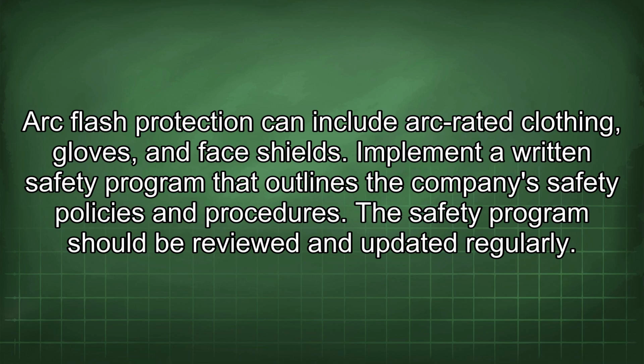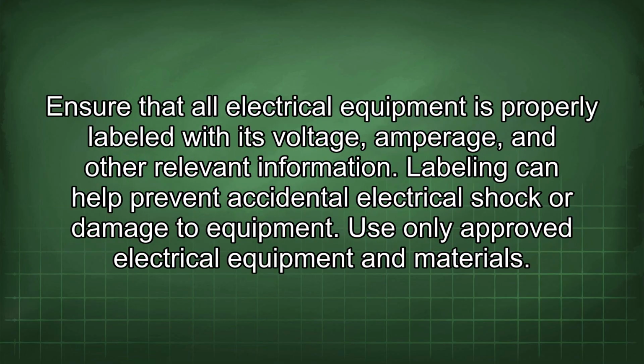Implement a written safety program that outlines the company's safety policies and procedures. The safety program should be reviewed and updated regularly. Ensure that all electrical equipment is properly labeled with its voltage, amperage, and other relevant information. Labeling can help prevent accidental electrical shock or damage to equipment.